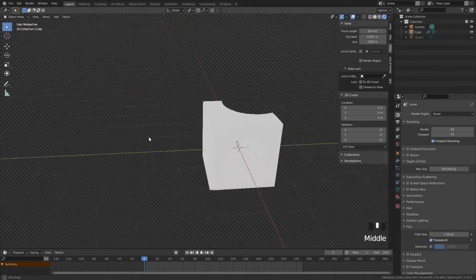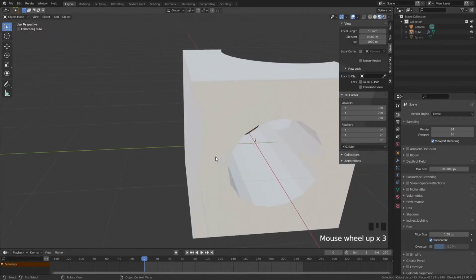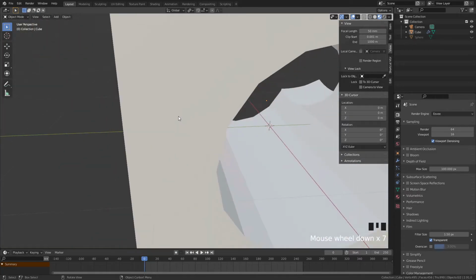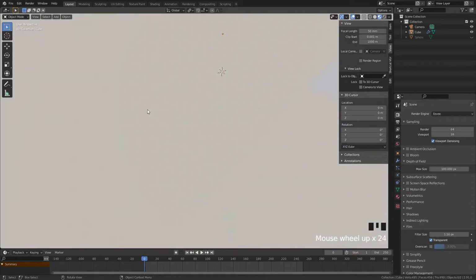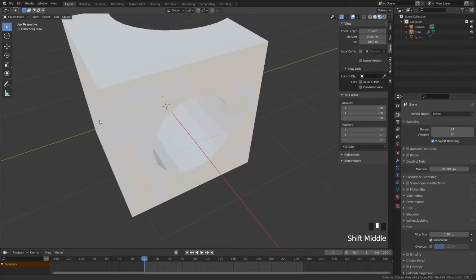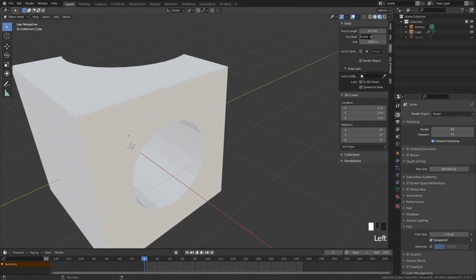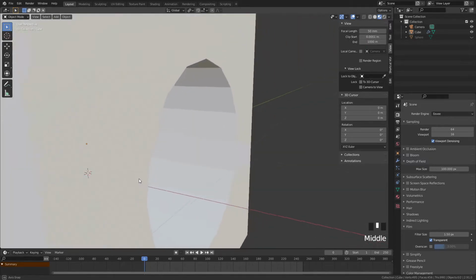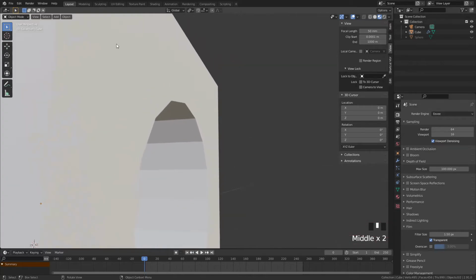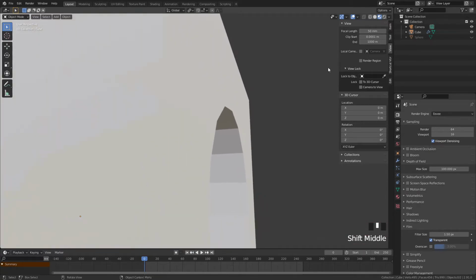And the next thing I want to say is, sometimes you are close to the mesh, but accidentally you see inside the mesh. That's because by default this one is very large, so we should change this one to 2.0. You just make it smaller, then you can see the subtle details on the surface. Yeah, just change it.